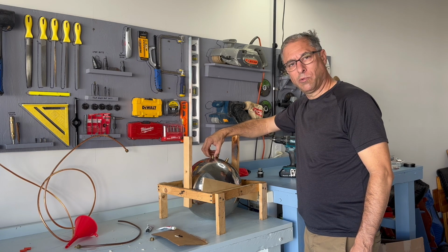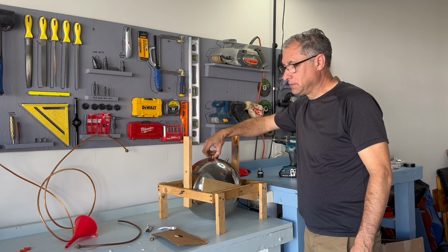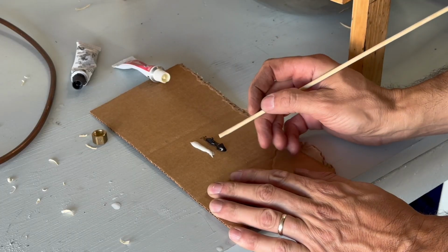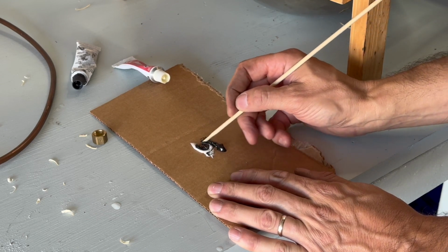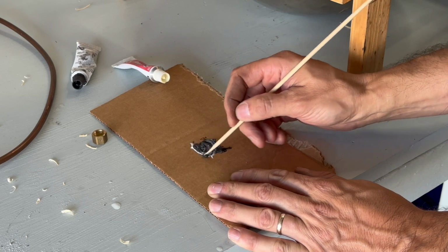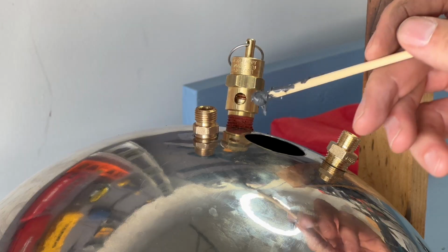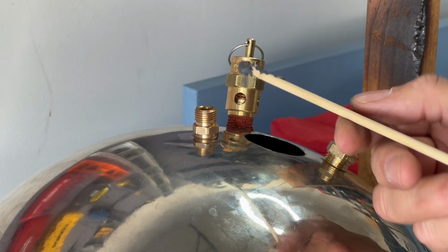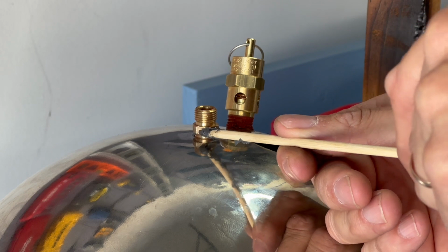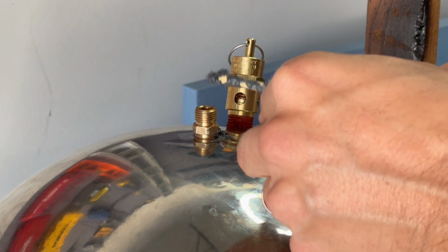I could put a couple washers under there, or I could just use the JB Weld. I have the JB Weld. I don't have to spend any extra money on it. This is my first time using JB Weld, but my dad showed me how to use it. So you just mix equal portions, and we'll just take a dab of that. It won't be pretty, but hopefully it'll keep the steam from leaking out. We want this to be pretty much steam tight.